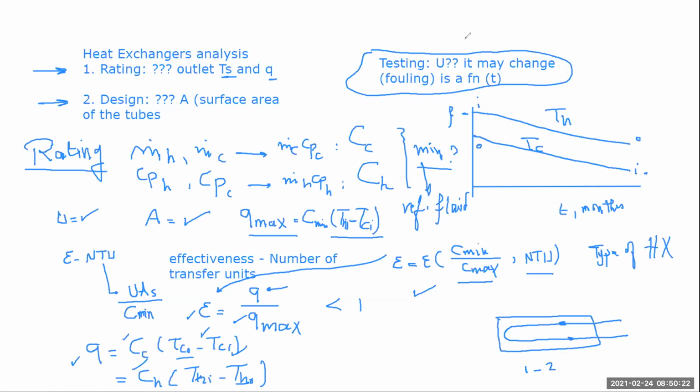Okay, so for the next slide, here basically I'm going to talk briefly about heat exchanger design. And by design here, people like us working in the thermal area call it thermal design, which means that I'm not calculating the stresses of the tubes and how the tubes are installed and welded and what should be the thickness of the heat exchanger shell. No, I'm not looking at that. But by thermal design, I'm only looking for how much the surface area of our heat exchanger should be.